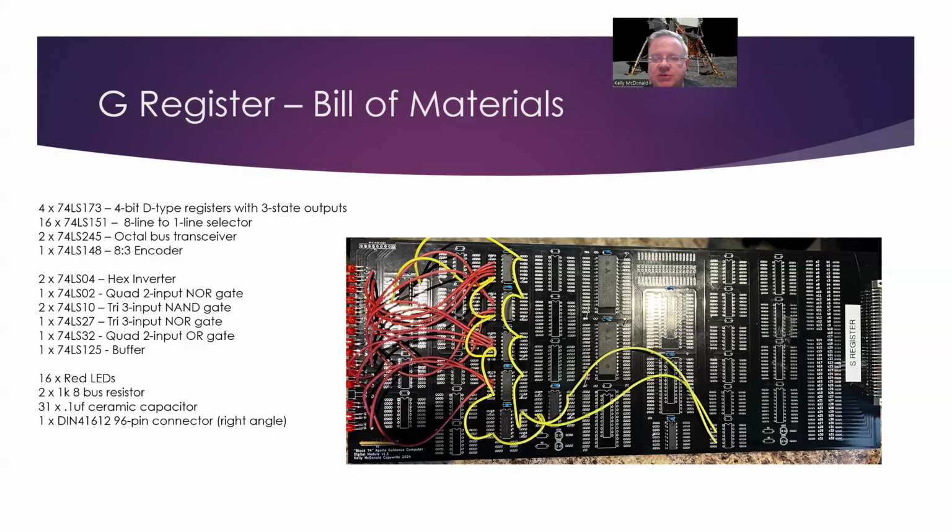And the way that these branch registers are set is there's a number of sub-instructions that perform a variety of different tests. So you can evaluate, is the contents of the accumulator 0? Is the contents of the G register 0? Is it a negative number? Is it a positive number? So there's several of these test control pulses that evaluate the contents of a variety of different registers, and based on that particular test, it will write certain patterns into those branch registers, and then those branch registers will be used to generate specific control pulses for evaluating whether the instruction should execute one way or execute a different way. But that's what we'll cover in the next episode.